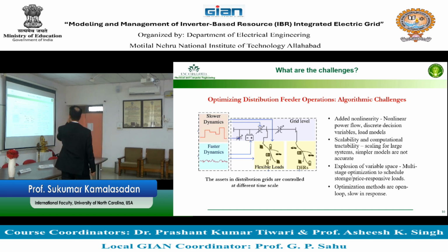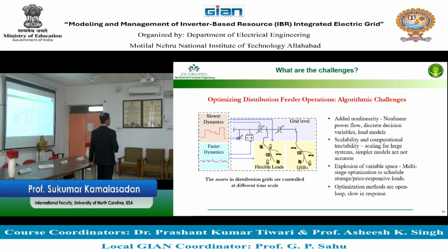Okay. So this is how the optimal power flow generally can work. What will be the output of an optimal power flow? What will be the output of a power flow or optimal power flow? The output of this optimal power flow, or power flow when you run it, will be a bunch of set points or reference points that go onto the devices in the field.